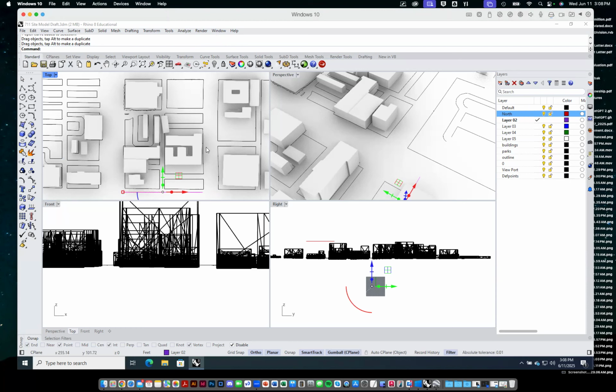I'm going to make this block and just redraw and clean it up without all these stray weird angles that are just slightly off. Then I'm going to use the fillet command and give them a radius, as street corners have. And then here's what I would do: think about that pattern, right?